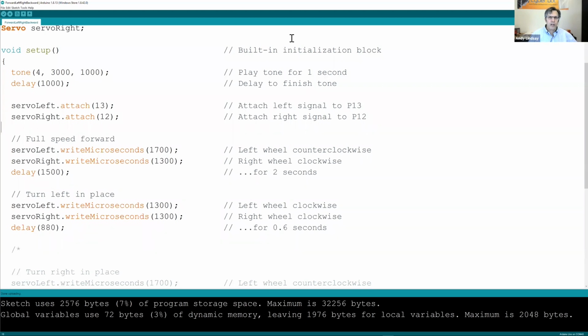The Arduino doesn't work great with the Feedback 360 servos. It's an older processor that has some shortcomings, both in the amount of code it can run and the speed it can run the code, and so on, so it's just not very compatible with the Feedback 360 servos. So I'd definitely be looking at the Activity Bot, which comes with Feedback 360 servos.